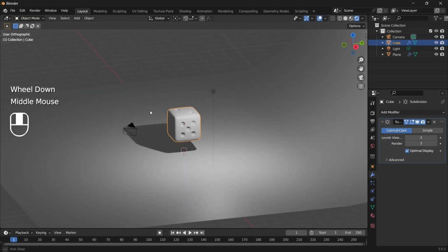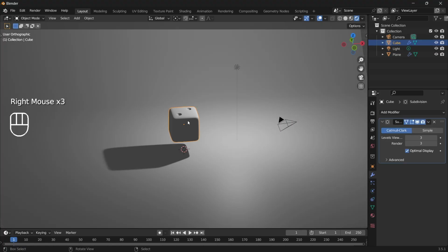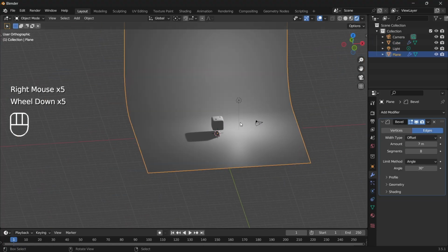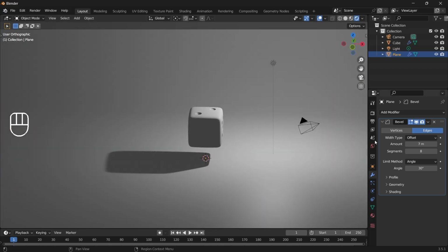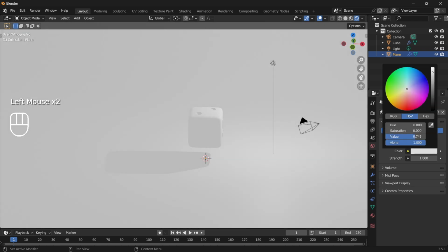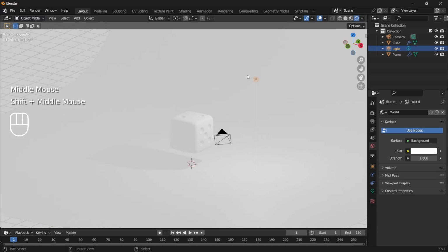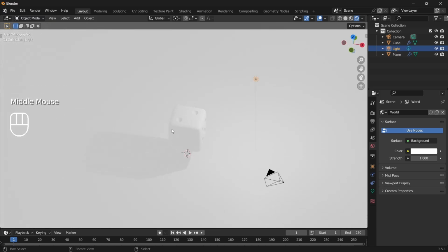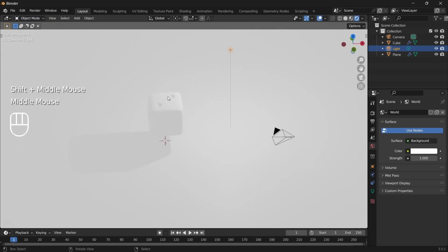And as you can see, our scene already has a light and a camera set up in it, but everything is a little bit dark and kind of dingy looking. So we're going to fix that by coming over here to world properties and setting the color all the way to white. So we just slide the color up to white, and now our world is not so dark, but we still have some shadows around to give us a sense of dimension in 3D space.